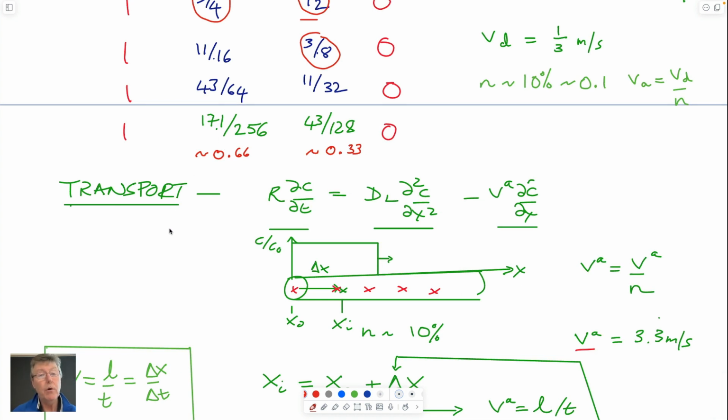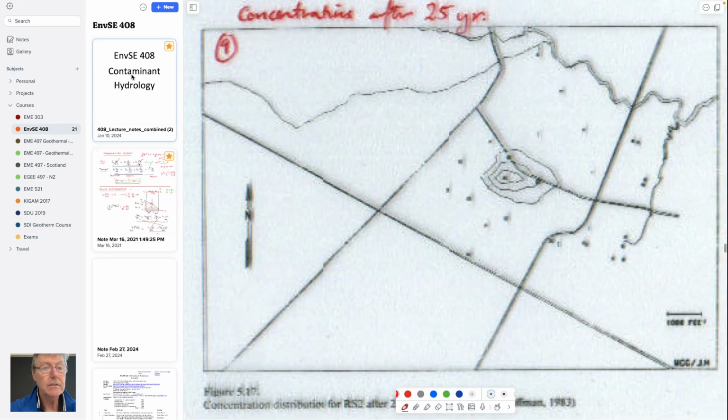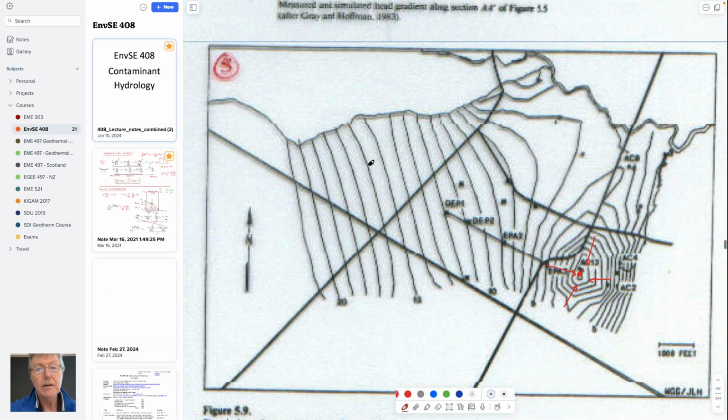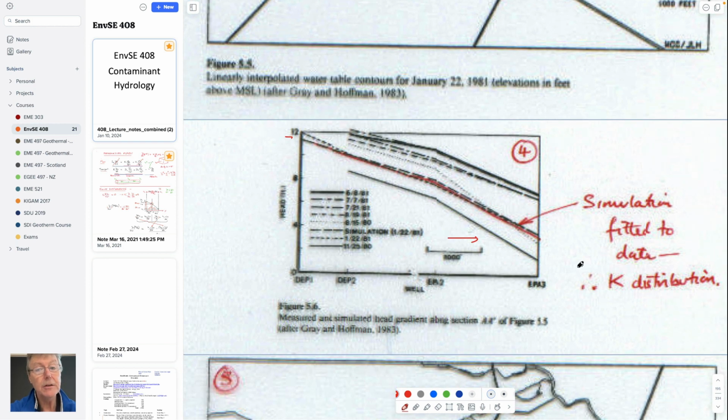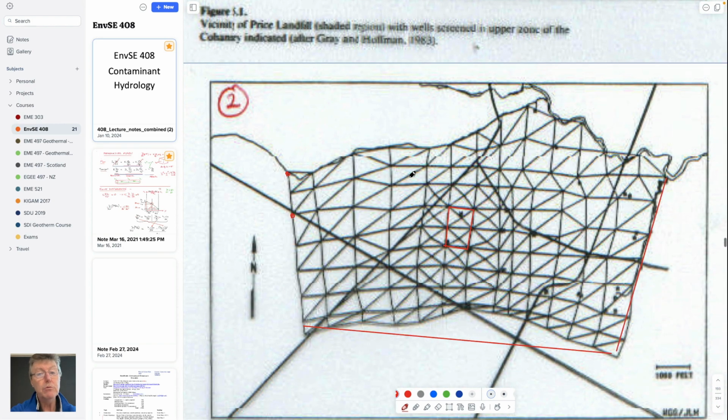And so now what we have is really rather like the section through our site that we had before. We had these water table gradients. As you go from upstream to downstream, the model now represents the in situ hydraulic gradient that you could measure. And if you apply this model by using a grid, the grid would look just like a lattice square grid in this particular case. You'd go individually around every single point, sum up the 4 surrounding nodes, add them together and divide by 4, replace the central node, and keep on working through the grid. You'd end up with a distribution of heads that would satisfy that 2-dimensional PDE. So that's what we've basically done.